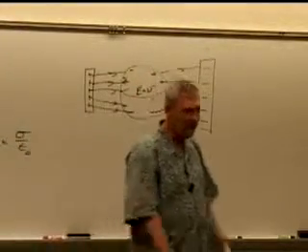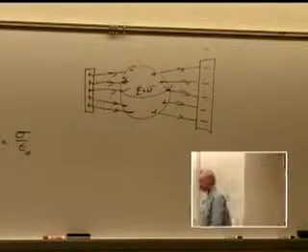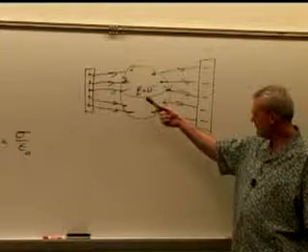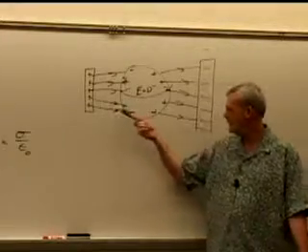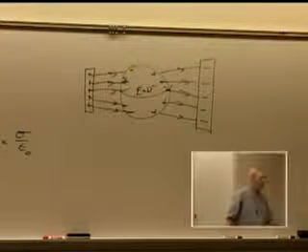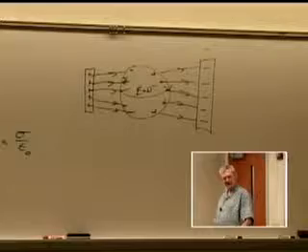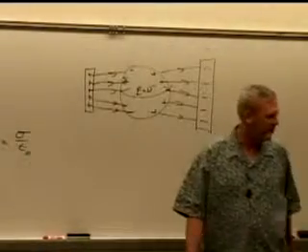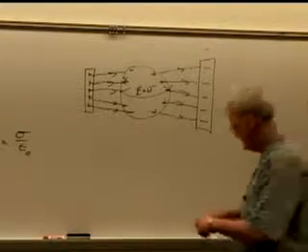Most people think, oh, well, I'd want it inside rubber or something like that. No, you don't want that because the electric field just passes through that. What you want is a conducting thing so that all the electric field collects on the surface of it, and what's going on inside isn't touched, doesn't harm it. Yeah, exactly, that's what that box is, to protect that circuitry. Okay, so that's point number 3.